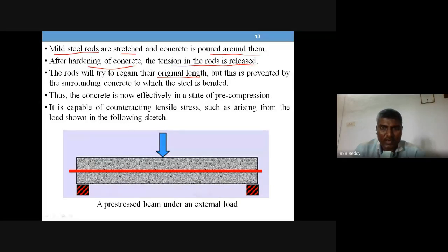As the rod is embedded in hardened concrete, the surrounding concrete prevents it from regaining its length. Hence, the concrete will be in the state of pre-compression.